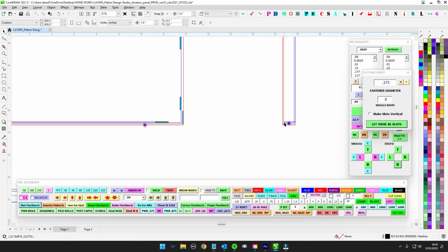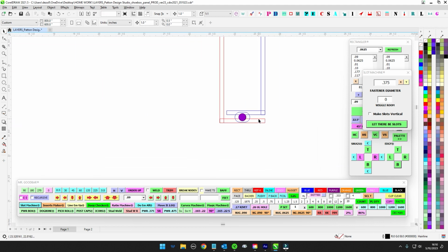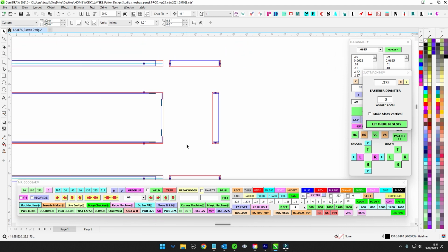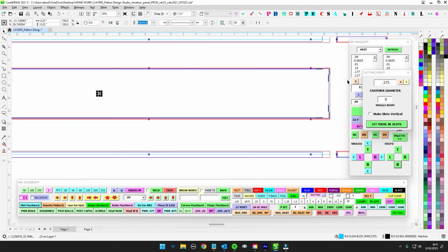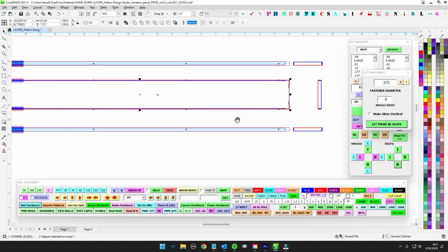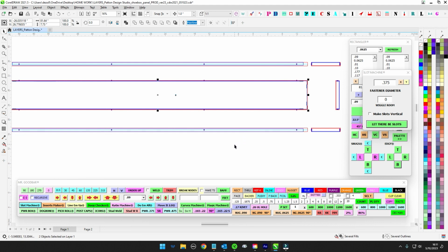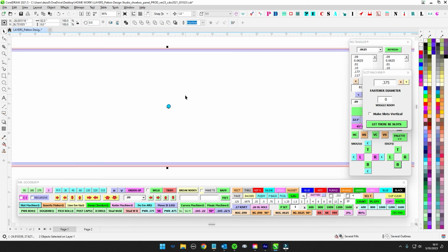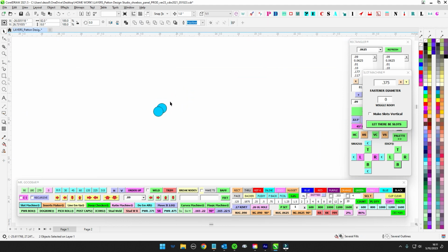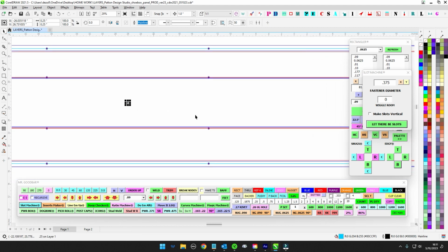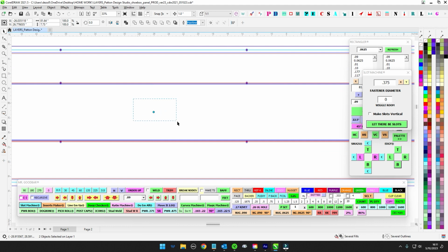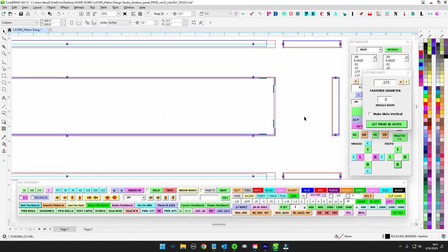Here's where, again, it's important to work with the backer or the face, because we are off center now. We're justified here. So you need to make sure you're working with either the face or the backer when you're working with centers. If I select the backer and hit center, that's one result, but if I center it to the face, then you can see where it's moved. So make sure you're working with the backer when you're centering things up, and you're not accidentally selecting the face.